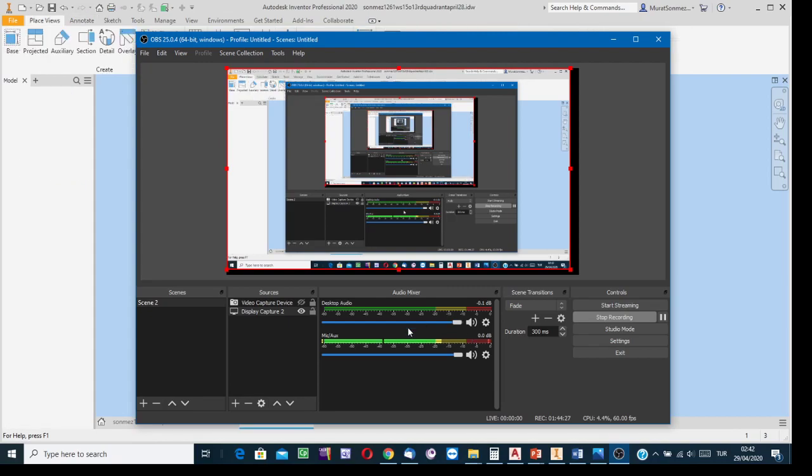Okay, dear students. I hope I managed to demonstrate how the model is created applying not the cutting but the material adding technique, partially cutting, partially adding, for such a geometry for which the pure cutting method is not suitable, because there are some curved surfaces, and also the other reason, the volume of the part to trim is too much. Then the adding method is recommended. And also I demonstrated one more time how the views are created in Inventor.